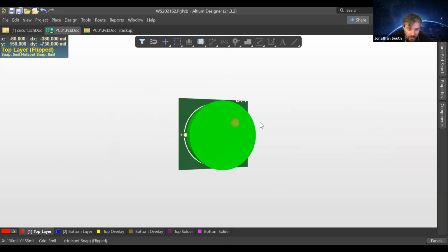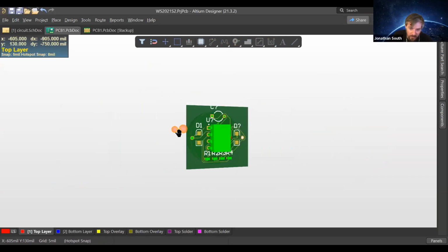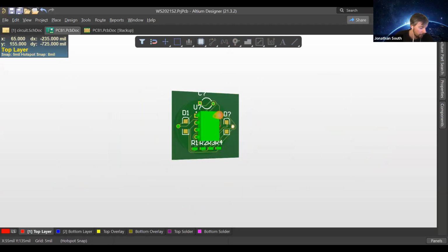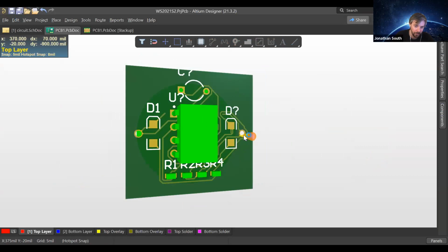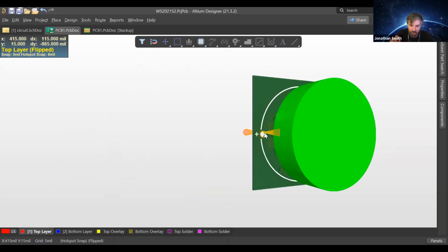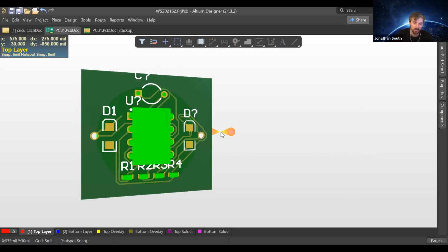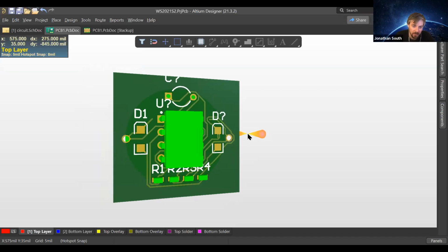Yeah. So the only thing you'd need to be aware of is the clearance with the through hole legs coming through, because if you think about how the chip's legs look when they come through, they do protrude on the other side by maybe a few millimeters. And if you're physically putting something on the back, you need to make sure you've got clearance around that. So depending on the choice of battery holder, there could be some mechanical collision issues there. Nice. Right. Looks good otherwise. So yeah, basically routing as we need to.